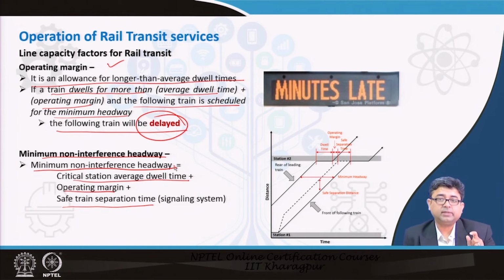And you should not tinker with that minimum headway, because the trains are usually at higher speeds, so it becomes very difficult for you to decelerate at the given time, and it may cause a collision with the train ahead of you. So, always maintain a minimum headway, keep that in mind even when you are designing for maximum capacity, right. Capacity, remember again, higher capacity should never come in the way of lowering safety.